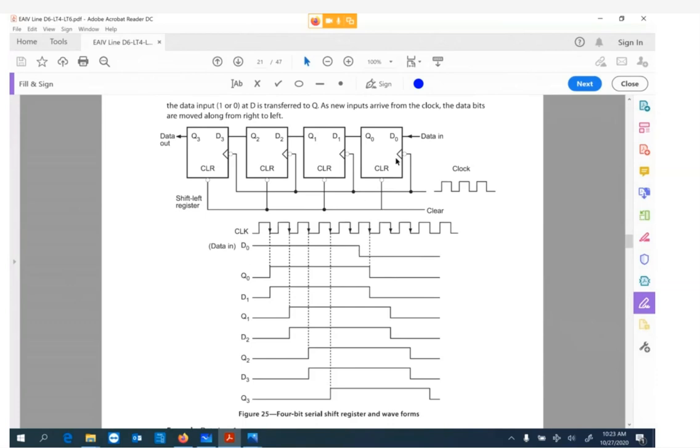So it's tracking, in this case, maybe tracking a board. But it's a 4-bit serial shift, and it takes 4 clock pulses to shift that data all the way over. So as long as D stays 1, they're going to make all these outputs turn to a 1. And if data goes 0, then the zeros would shift over to the left. And notice once again, the little inverter gate makes it trailing edge trigger.